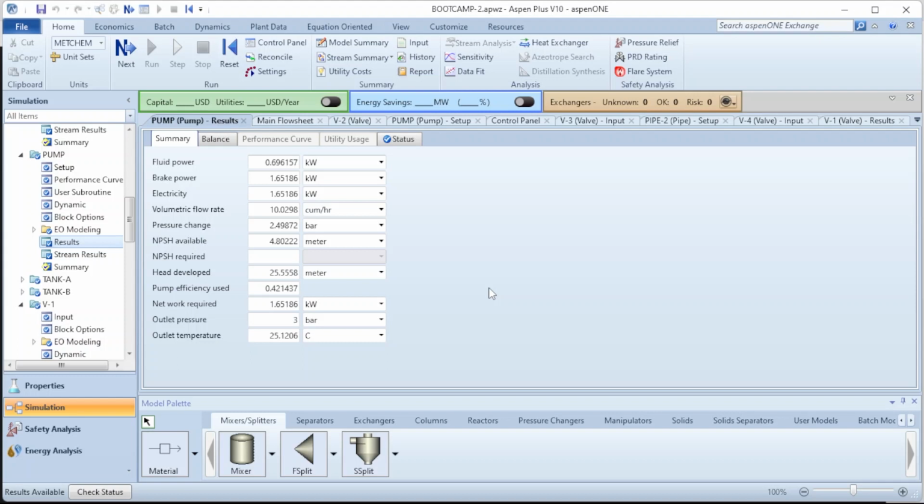But looking at the NPSH that's required in order for cavitation not to occur in the work that we are going to do is 4.9. And based on that, you can tell your boss that in order for cavitation not to occur, the NPSH available should be greater than the required. And since it's not that, cavitation can occur. You can tell your boss that.